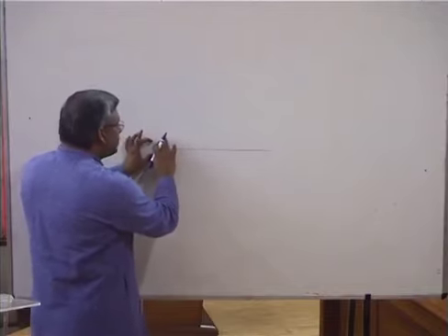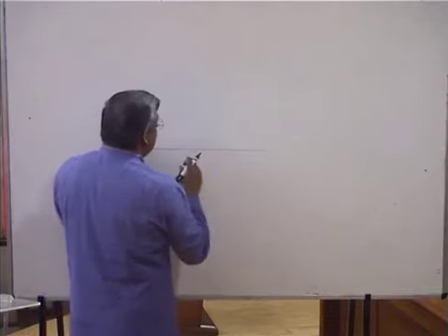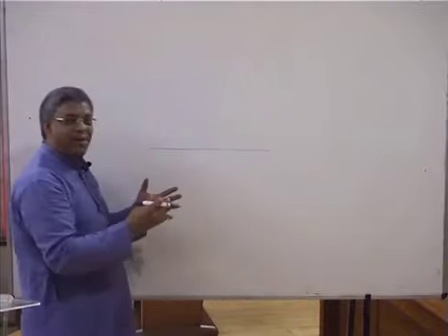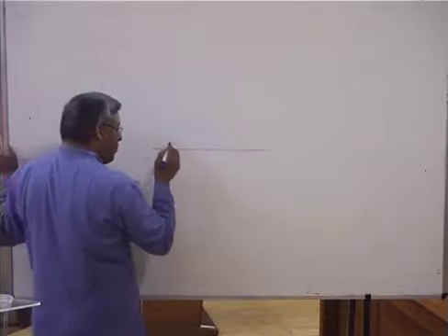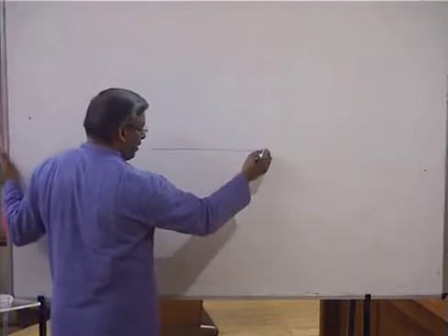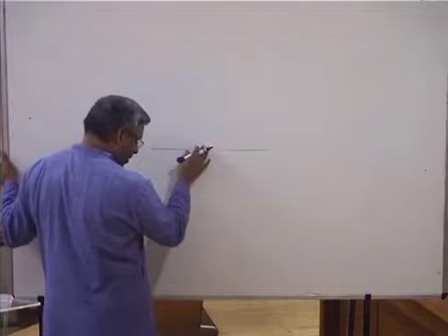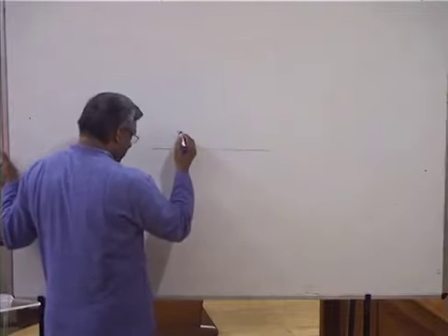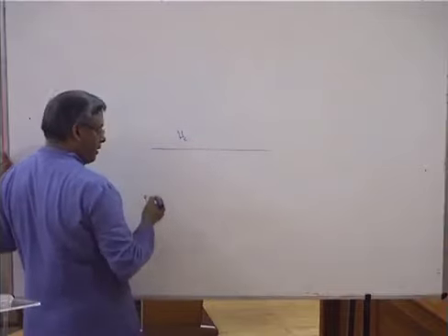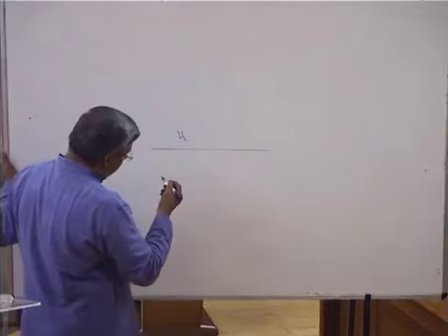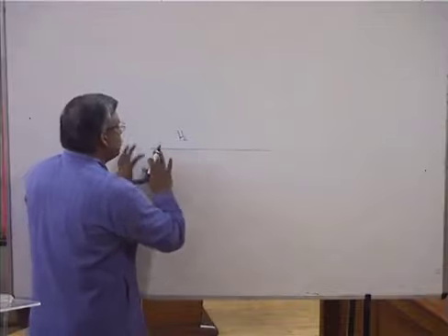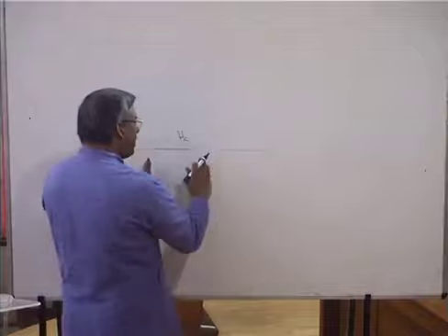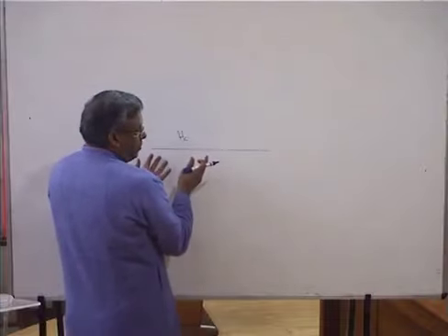Then you can imagine there's no resistivity for this wire, so you may think an infinite amount of current can be carried by it. Absolutely wrong. When current is carried by a superconducting conductor like this, there will be an associated magnetic field developed. If this magnetic field reaches a value greater than Hc, the superconductivity of this material is gone. The wire becomes a normal conducting wire, and therefore you cannot carry an infinite amount of current.